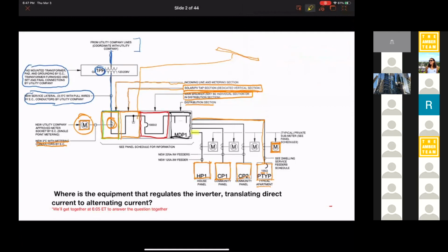We're also going to go to a house panel, and the house panel is for that particular apartment building. So there may be emergency lights on that apartment building, or a trash compactor for everyone in the building, or just the electrical receptacles in the hallway of that building that are going to feed the vacuum cleaner when the maintenance staff vacuums the hallways.